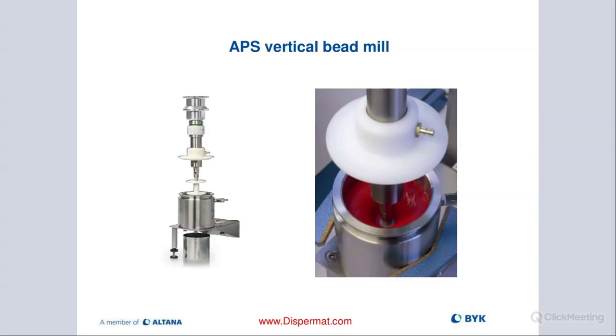And then when we are cleaning, also very easy, we just put the drain plug back in place, fill our container 50% with cleaning fluid, close it up again, and run it with the beads for a few minutes. We flush it out, rinse, repeat until it's pretty clean. So that allows us to efficiently clean that vertical bead mill without having to disassemble anything.